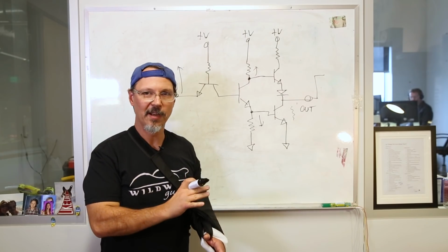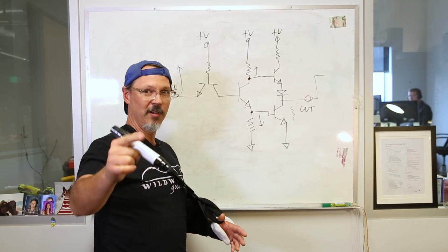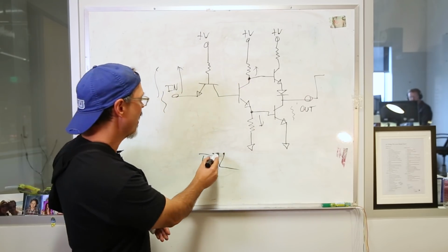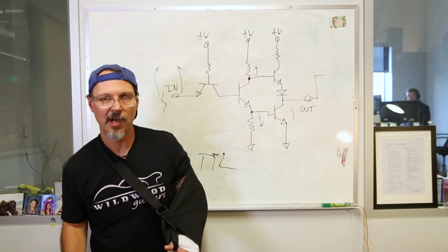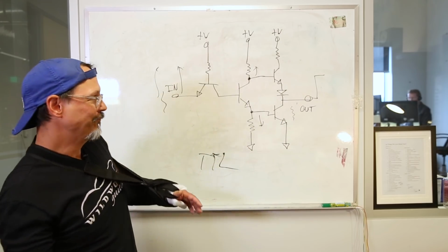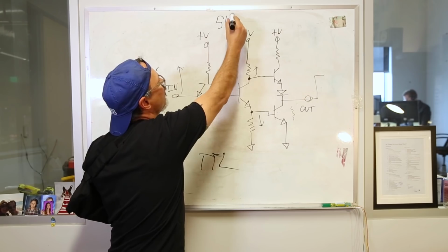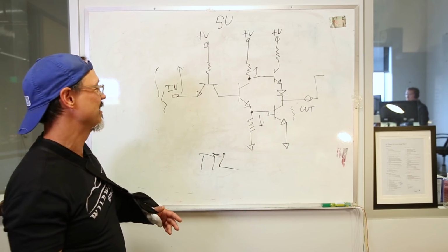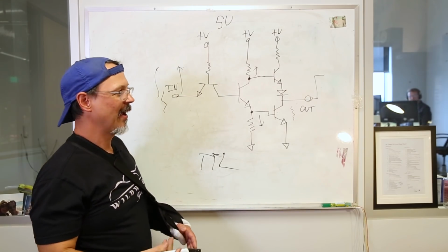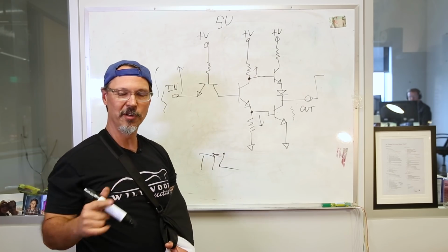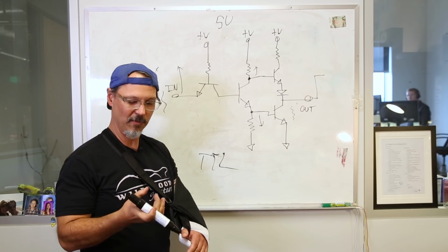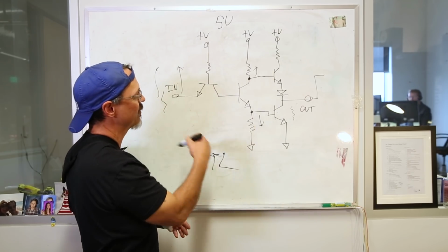Now, this is an example of TTL logic. What's TTL? Most of you are not asking this question. TTL stands for transistor-transistor logic, and it is characterized by the use of bipolar junction transistors, and generally with a power supply of around 5 volts with associated thresholds that we're not really discussing right now. TTL was really popular back in the day. Before I got a 4-year degree in engineering, I went to technical school, and we learned digital logic using TTL parts, discrete or monolithic parts that have this function.